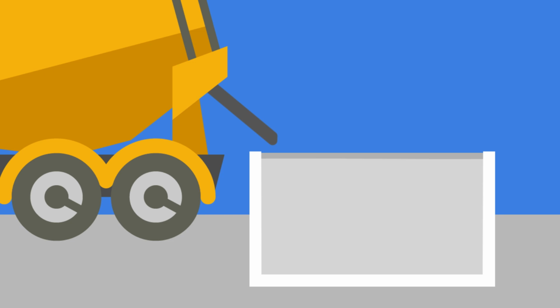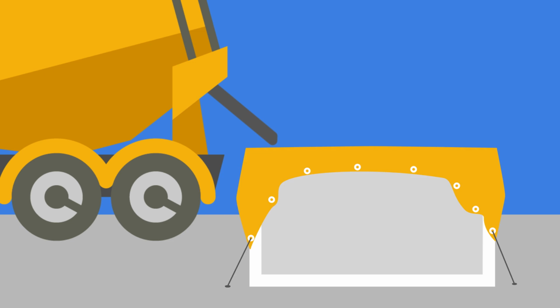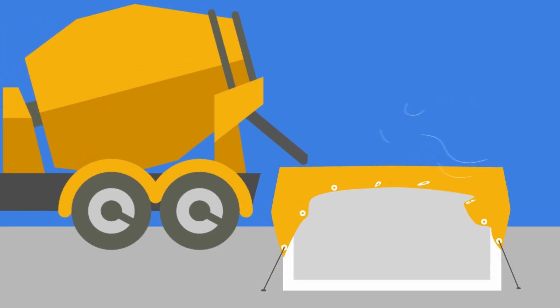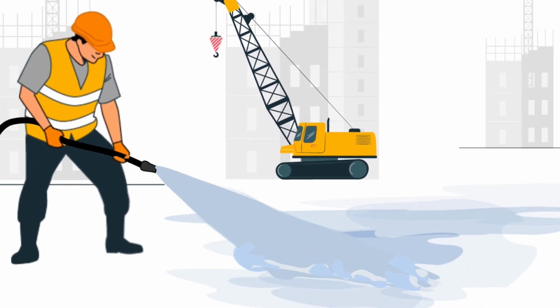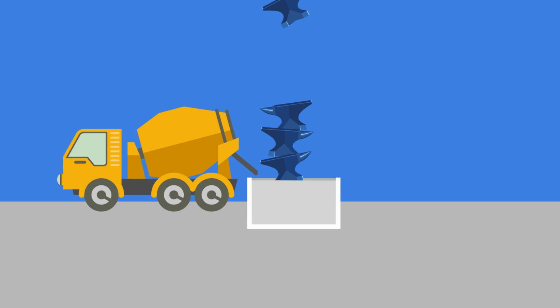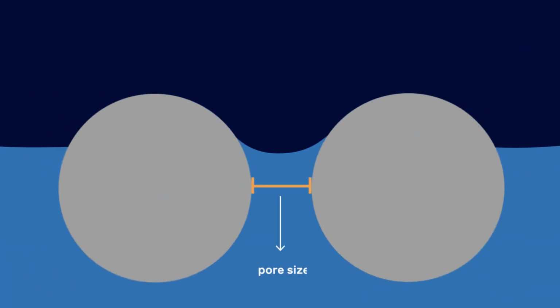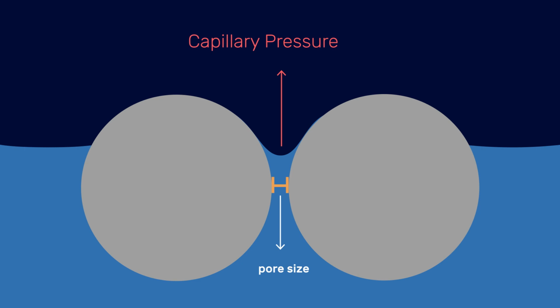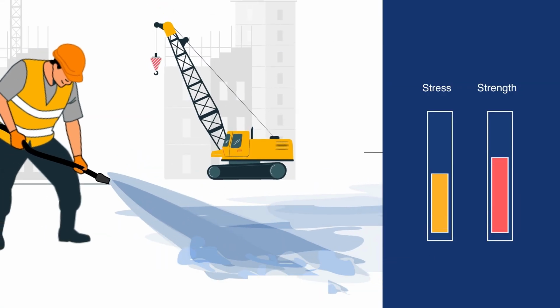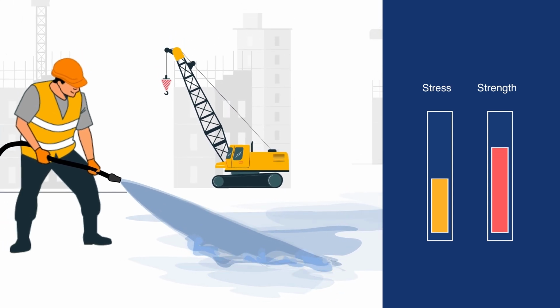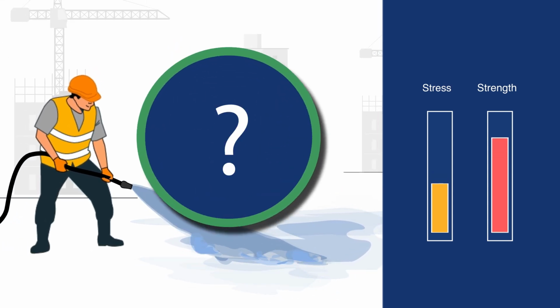Prevention of rapid drying of freshly cast samples is an effective way of limiting plastic shrinkage of earthen or cementitious materials. This may comprise covering their exposed surface, protecting them from wind, or actively keeping them moist by spraying water or a curing compound. After hardening, the strength of cementitious materials is much larger, but its pores are smaller, so that higher capillary pressure is generated during drying. Unfortunately, the amount of curing needed to raise the strength more than the stress and thereby avoid damage is difficult to predict.